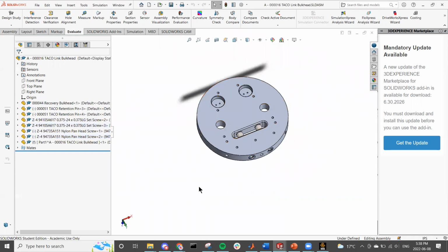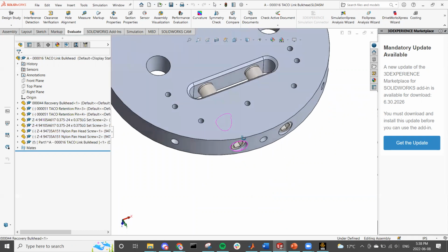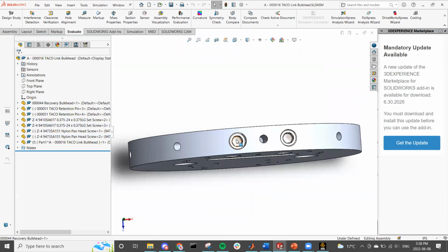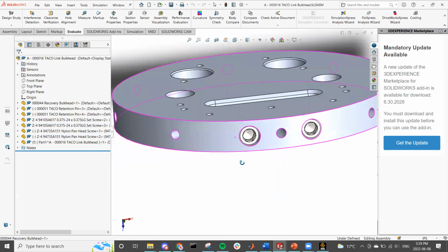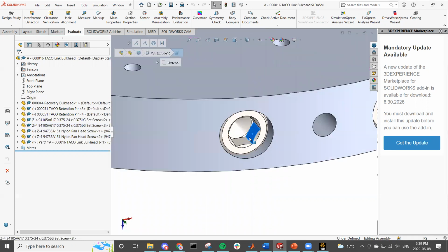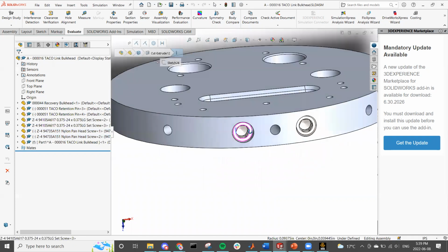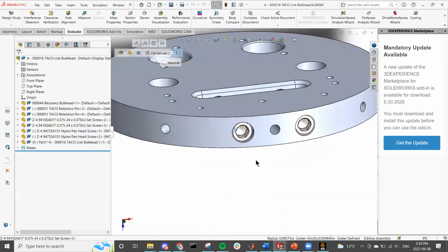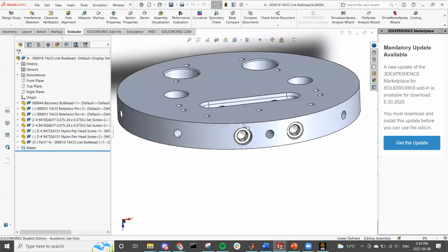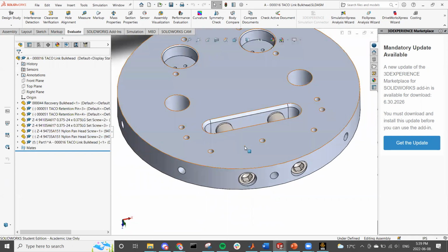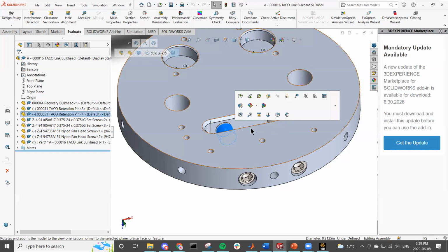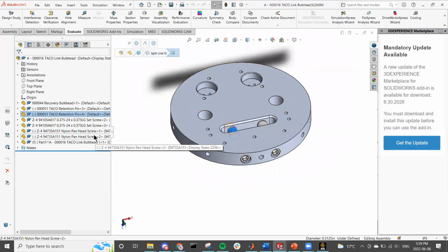If you do an assembly, you want to take out any unnecessary parts. For example, these don't really add much structurally, so we can take them out, because you can see this has a number of extra faces and you're just adding more bodies. The more interactions you add, the more complex it is. So if you can delete things, definitely do. However, I do not want to delete these pins because they interact with the bulkhead. These fasteners, not so much.